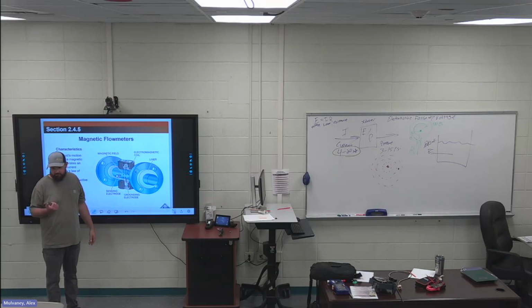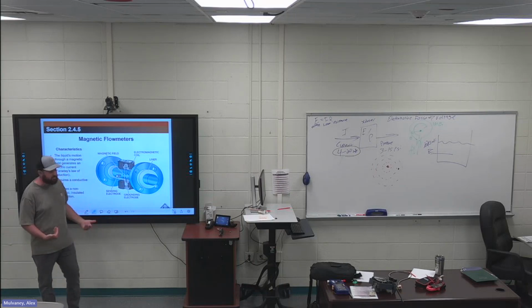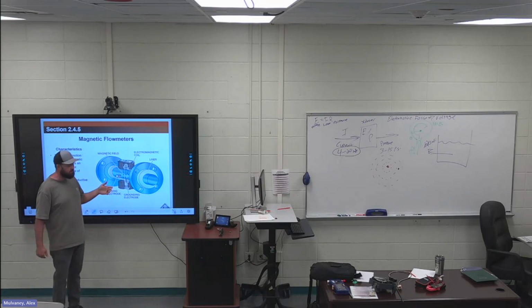Is water conductive? Yes. If you're standing in water with your bare feet and you throw a cord on the ground, you're going to get shocked. It's conductive; it's going to pass electricity through it. So say you have water flowing through this, it's conductive. It's inducing a field on this coil, and based on that electrical field, we can determine a flow.